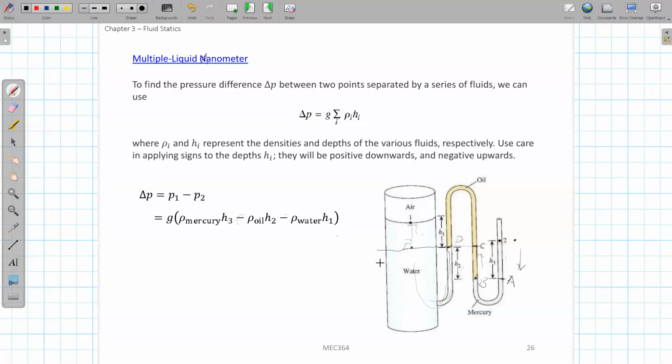It's water. Okay, and also if we said that there's the atmospheric pressure, this equation doesn't take that into account. Yeah, no. If it has 1 atm here, that means that this value is 1 atm. So your P1 will be equal to this one plus this 1 atm. So this value only gives you P1 and P2. Okay, thank you. No problem.